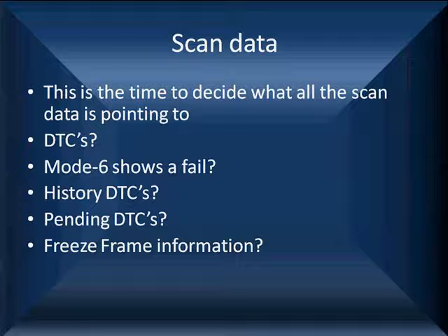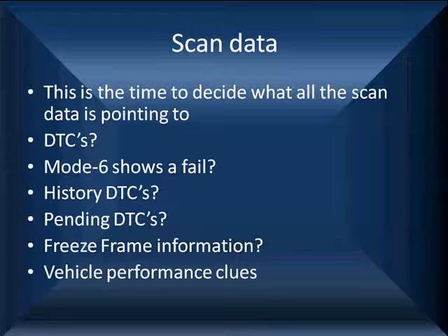Freeze frame data for fuel monitor is really valuable. It tells you where you had the problem. And the vehicle performance clues. Is it surging? Does it seem to have low power at high end? Rough idle? What all is going on?